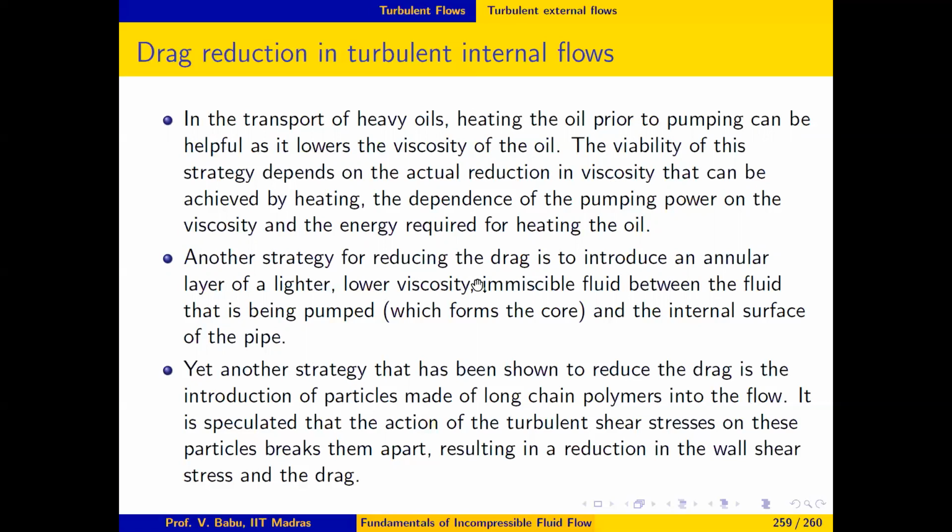Another technique that is used in the transport of heavy fluids is to introduce a very thin layer near the wall of the pipe of a lighter, lower viscosity fluid, which is immiscible with the fluid that is being pumped. For instance, if you are pumping crude oil, then we may introduce an annular layer of, let's say, water or some other lighter fluid, which has a lower viscosity, and being lighter, it floats above the oil.